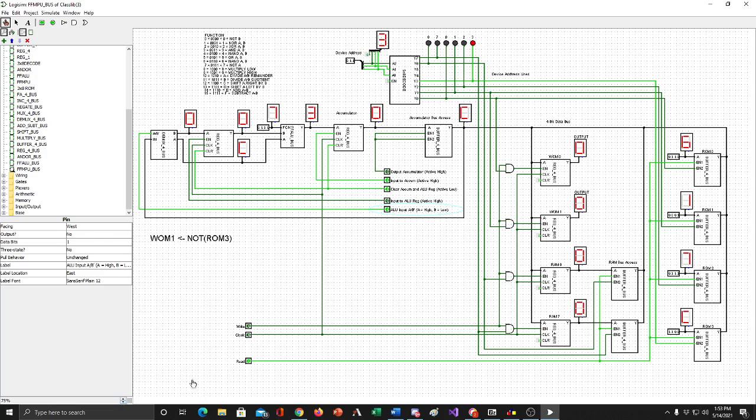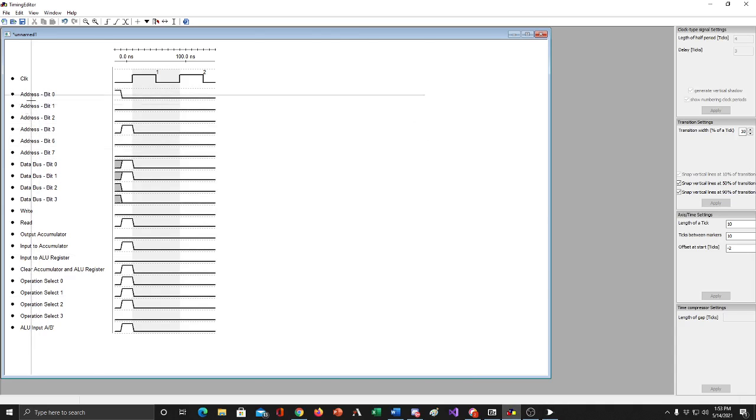So we're going to zoom out because we want to watch for what changes. So I'm going to clock this. And the only change is the contents of the accumulator, which is not any of the things we were keeping track of here. So it didn't change the address, the data bus, the write, the read, any of these control lines. So nothing actually changed on this rising edge.